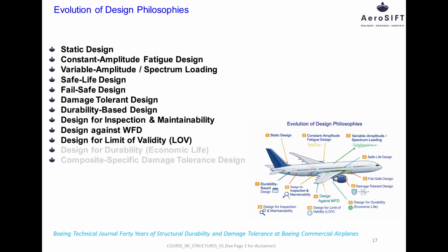The limit of validity concept establishes a mandatory operational life limit for an aircraft, beyond which it cannot continue service unless additional justification is provided. This limit is based on fatigue testing, service experience, and structural evaluations related to widespread fatigue damage. The LOV ensures that aircraft are not operated into regions of high uncertainty in structural behavior, reinforcing safety through defined retirement or extension criteria.